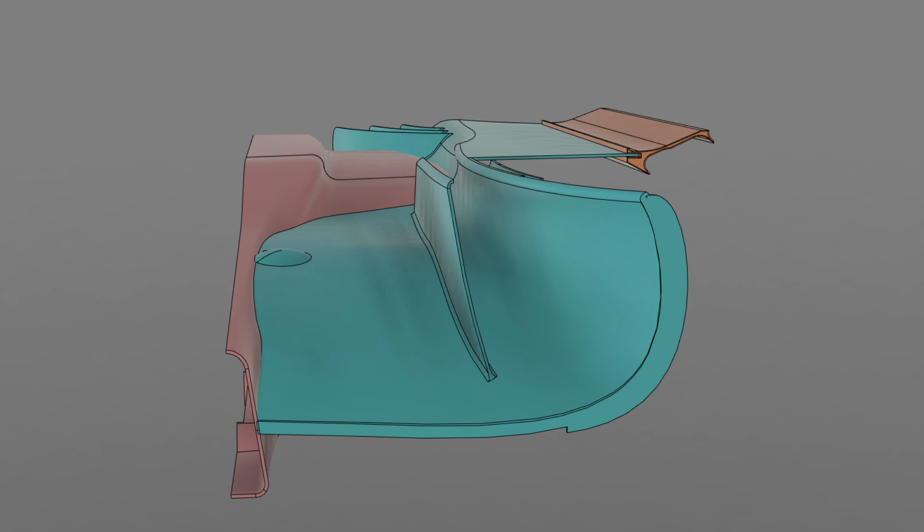ratio. The larger the expansion ratio, the larger the potential for generating downforce, as long as the air still remains attached to the diffuser, i.e. the boundary layer doesn't become too thick. This generally means a well-designed diffuser can have an expansion ratio of around 1 to 6. The lower the vertical height at the throat, the more sensitive the downforce becomes to ride height.